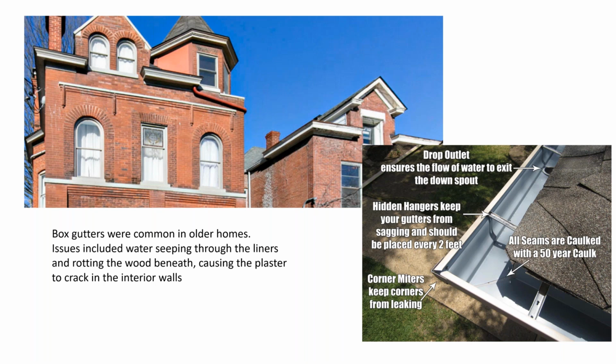And I have seen a whole lot of houses in St. Matthews where all the plaster's cracked off on the inside of the building, and it's because their gutters are not kept clean, and the water gets up underneath the shingle and it basically rains inside. So it's between the brick and the drywall or the plaster, and it will collect water and start to make that plaster pop.